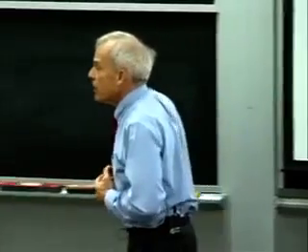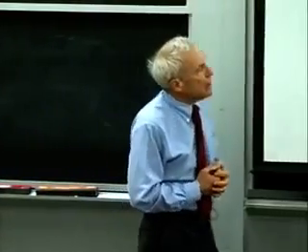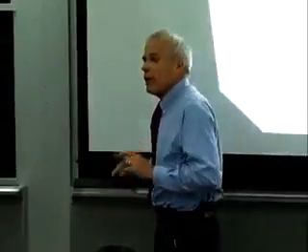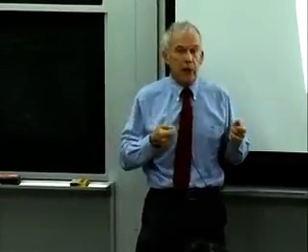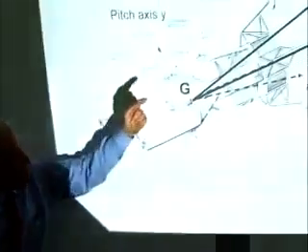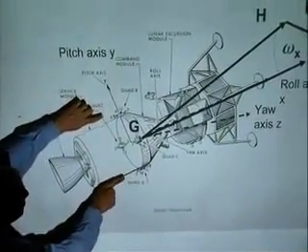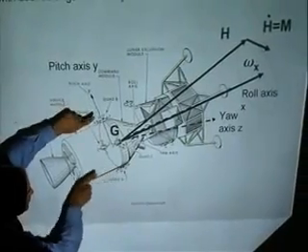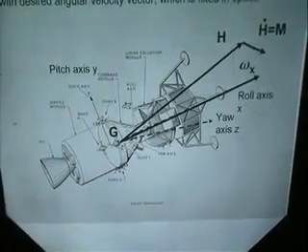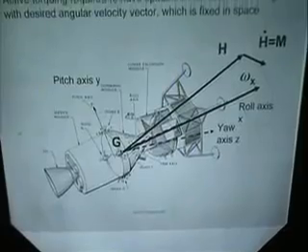I don't think you've talked enough about the fact that the jets were being pulsed. Yeah. And you guys did that on your homework, right? It was like once a minute or once every whatever you got in your homework. To deliver this average level of torque that was required to keep the angular momentum coning around, the jets only could be turned on and off, so you had to pulse them. Pulse, pulse, pulse. So on a time average basis, you would deliver that average torque that was required. And these are the jets here that would have to be fired, these little quads of clusters of 4 jets, so boom, boom. So the astronauts were hearing this bang, bang on the oil can, and they weren't getting any sleep. And they've got a 2-day trip to the moon going on.